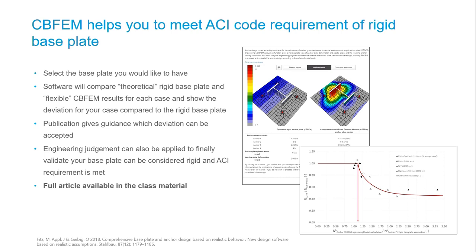Good. Why is the anchor also important? Let's just assume you have probably seen or used chemical anchors that are really glued into the concrete somehow, right? These are extremely stiff, so you have a very steep load displacement curve, and the anchor will not move a lot if you pull it. Then you have some sleeve anchors or mechanical anchors, where first it needs to be pre-tensioned or pre-torqued, and then the sleeve needs to move, and there is some movement in order to get the load transferred. These anchors have a completely different load displacement behavior.